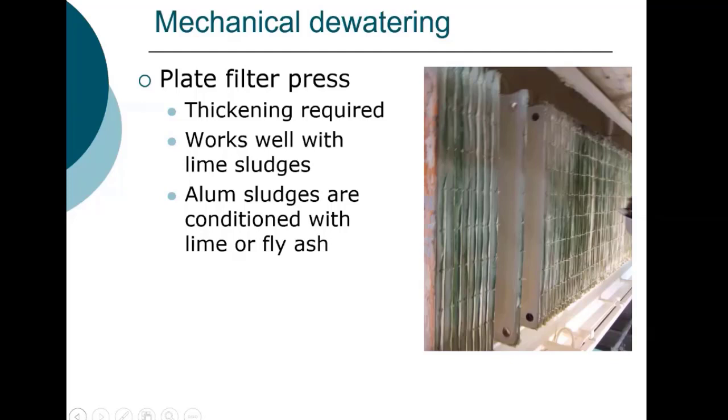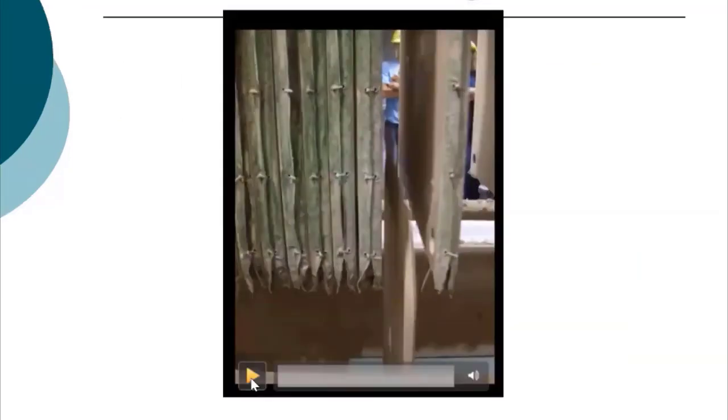Any cake that's left can result in areas where you don't get sufficient closure of these plates. And then when you apply the pressure, that sludge basically shoots to the ceiling. And we got to see the plant. You actually can see sludge on the ceiling where this occurred. Again, this is at the Dye plant.